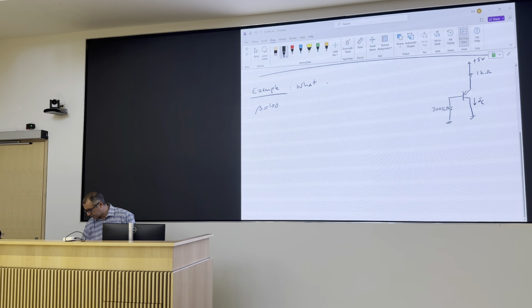If you use the right value for this VDO, or if you just read it off the data sheet, this number is going to be within a few percentage points of the actual value. And then you don't really need more accuracy than that. Because whatever resistor you choose has a tolerance. Whatever power supply you choose has a tolerance.